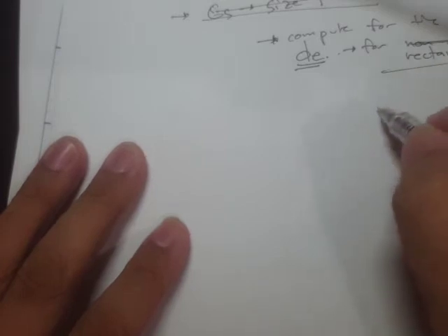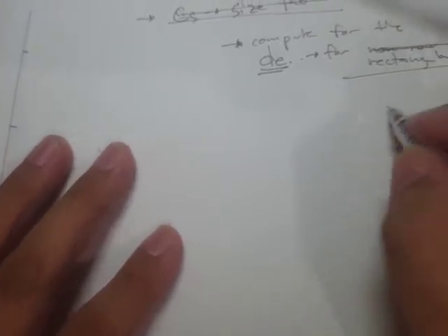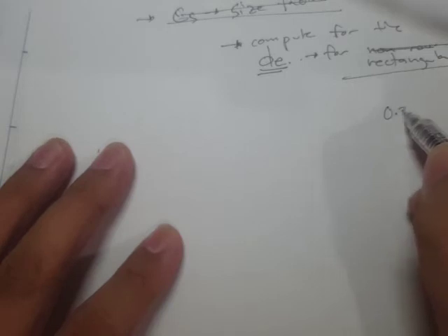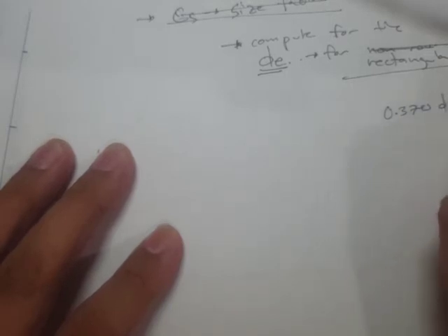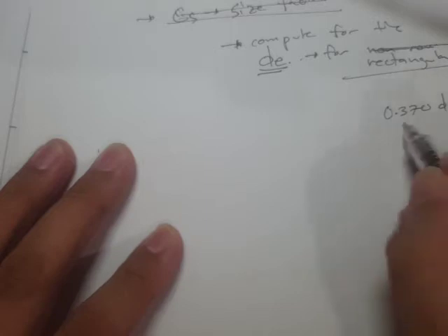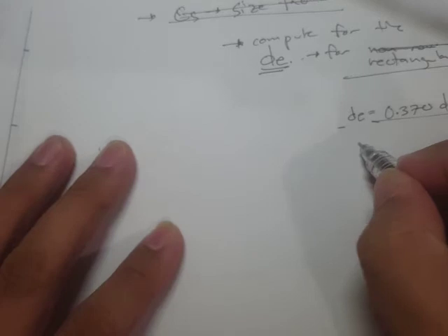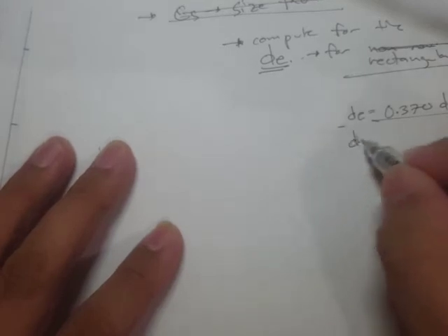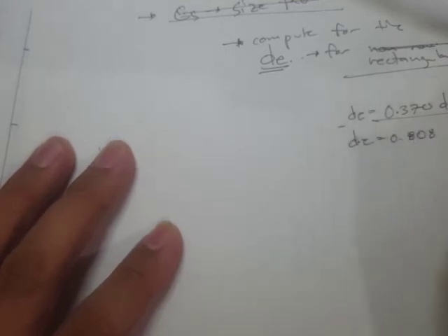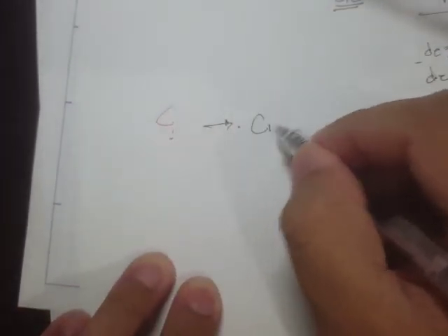We have this in our lecture handouts, and this is also taken from the textbook by, I think, Shigley. So for a non-rotating round or hollow cross section, the equivalent diameter is just equal to this, and for a rectangular cross section we have 0.808 times (hb)^0.5, where b is the base and h the height. Right, so once you have all this, then you just have to go to the table and select the appropriate equations.